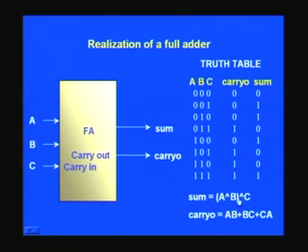And hence this expression is nothing but this. The reason this bracket is put is that in Verilog we can implement this using gate level primitives also. They are restricted to 2 inputs basically, and so in order to realize a 3 input exclusive OR, you will have to use 2 numbers of 2 input exclusive OR. And carry out is simply a majority logic, and you can easily infer the majority logic wherever more than two ones are there, you will see the corresponding one here, you can see it here everywhere.